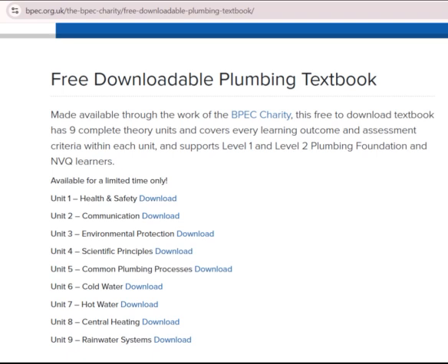British Standard BS EN 14336:2004, Heating Systems in Buildings, Installation and Commissioning of Water based heating systems is very specific with regard to the test pressures and duration used on wet central heating systems. It states, the heating system shall be pressure tested to a pressure at least 30% greater than the working pressure for an adequate period, as a minimum of 2 hours duration.